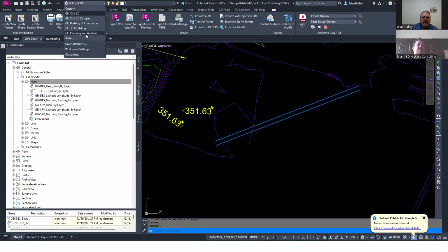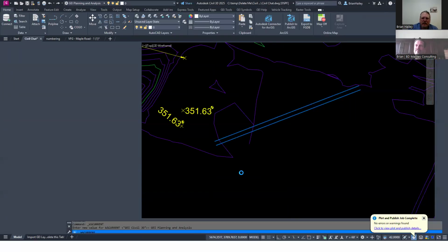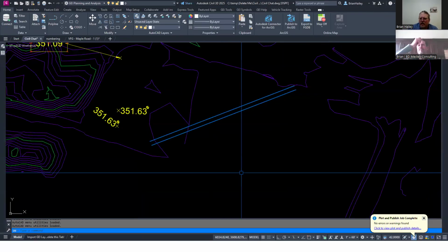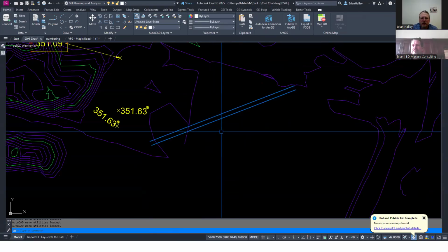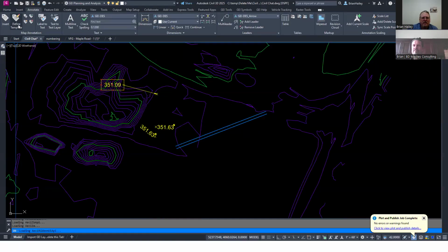Right. So like I said, if it is object data, which is the old Map 3D way of assigning data to objects, which is how we can assign object data to a block, within it you can come up here to the annotate tab, define a template, and then label all of the objects using the map annotation here. It's not something I'm super familiar with. I do know it's there, but I don't know how to convert the property set data into object data. Owen and Christopher are saying Dynamo, but obviously it's not dynamic.